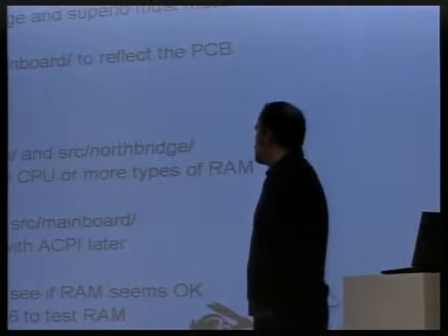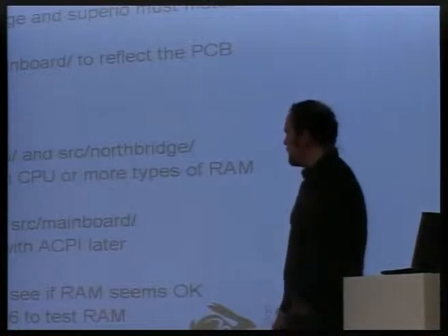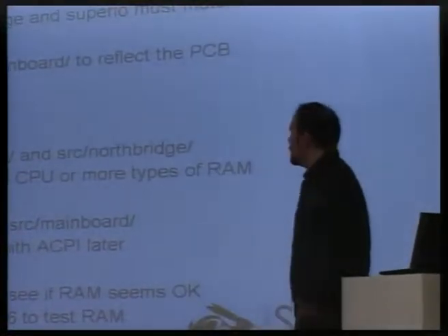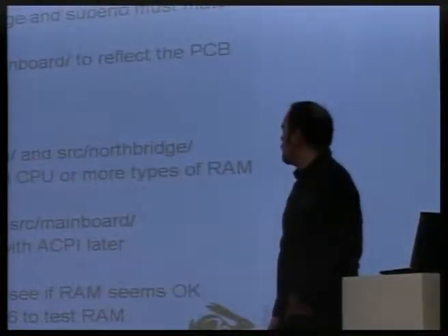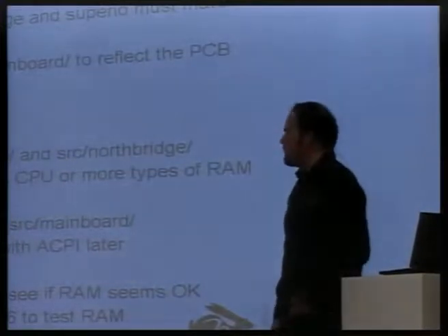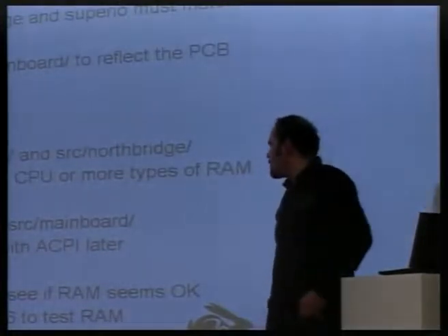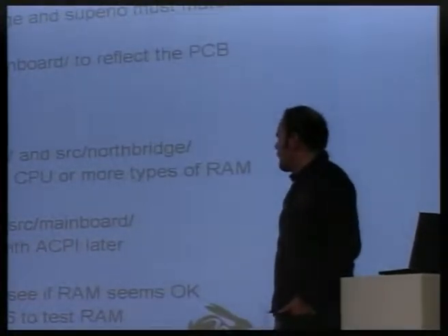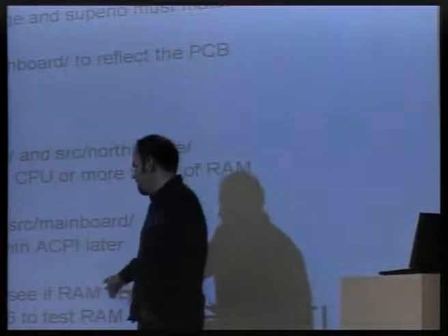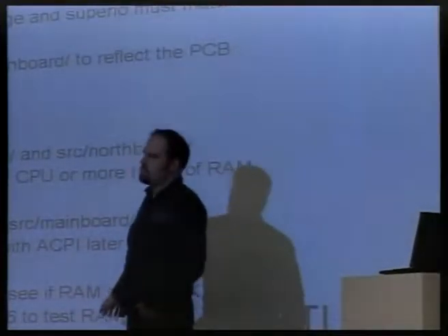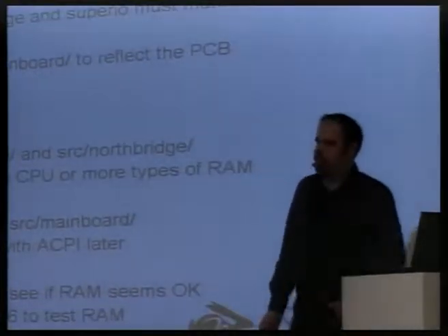Now, if you didn't need to do any of this code addition for the RAM controller, then Mem Test 86 might just run fine the first time. But certainly, if you're adding or changing some of the code for the memory controller, then it's important to do thorough testing so that you squash any bugs that might remain. It's actually fairly frequent to make it all the way to RAM check, and sometimes even past RAM check, without RAM actually working properly.